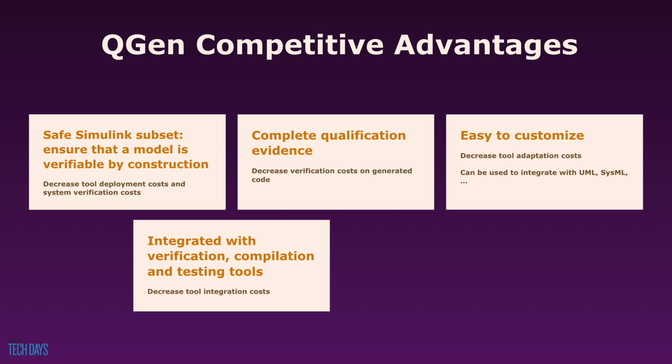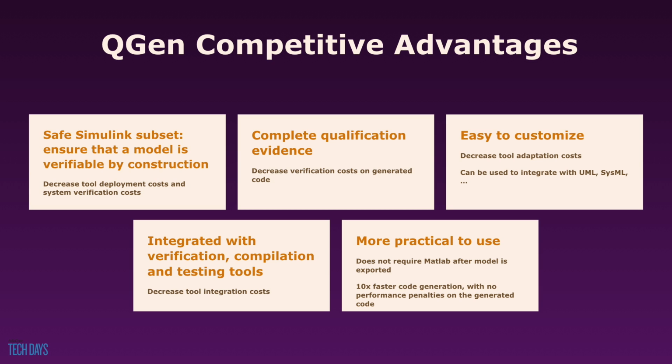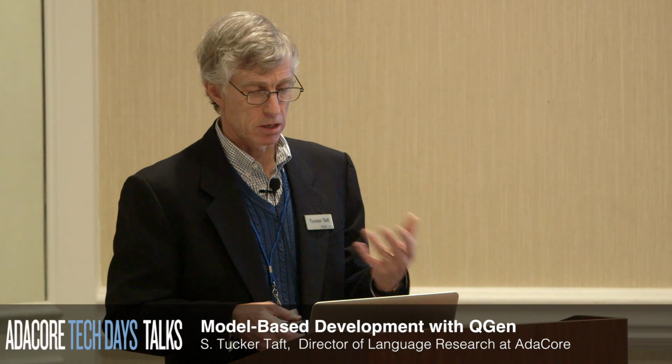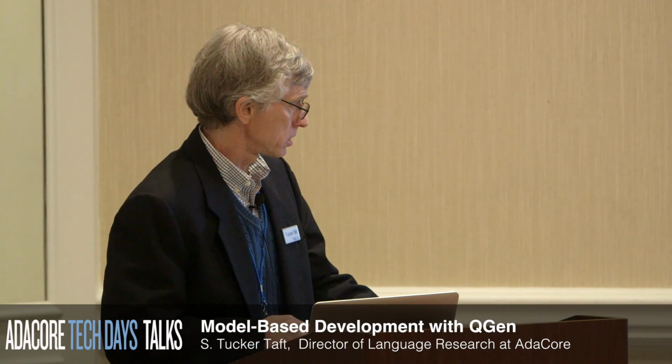One of the nice features of it is that it is a tool that you can use outside the Simulink environment. It is integrated with Simulink so that from the Simulink environment you can start QGen to convert a model into code, or you can do it offline. You can export your models into a MDL or SLX representation, and then everything can be done from then on offline. And I'll show you some examples of that.